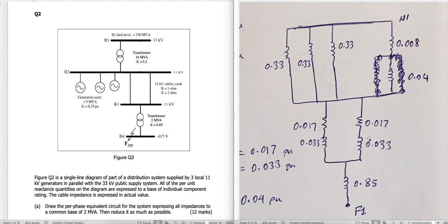So, for example, if I go to calculate these parallel and series impedances, firstly I pick these 3 impedances. When there are n parallel impedances with equal values, the equivalent one equals the impedance of one of them divided by the number. So if you have, I don't know, 10 impedances, and each one is just 100, then the equivalent one is 100 divided by 10. You take the impedance of one of them and divide by the number.